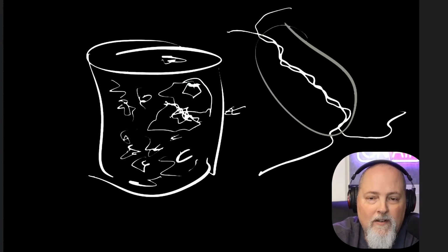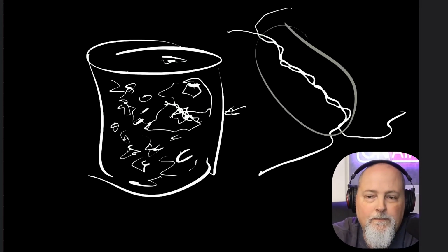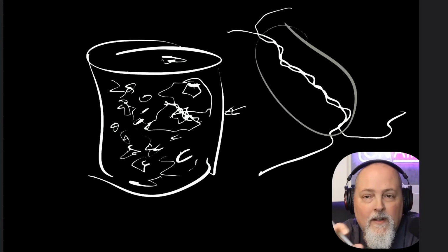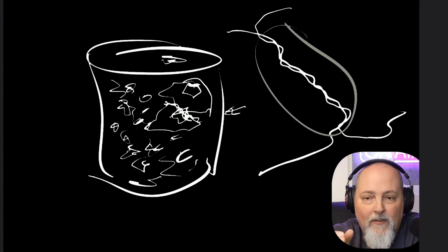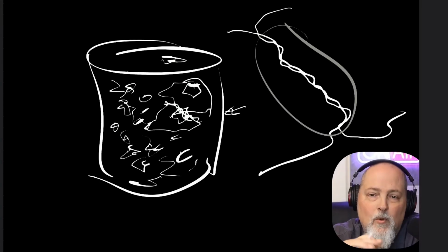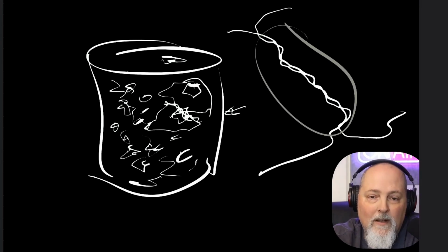Rapid cooling tends to create a lot of small, fine grains. Slow cooling tends to create larger grains. And like I said, those grain structures can inhibit slip, can strengthen a material and make it stiffer, basically. And so a lot of really fine grains due to rapid cooling can make it stronger, make it less likely to be ductile.